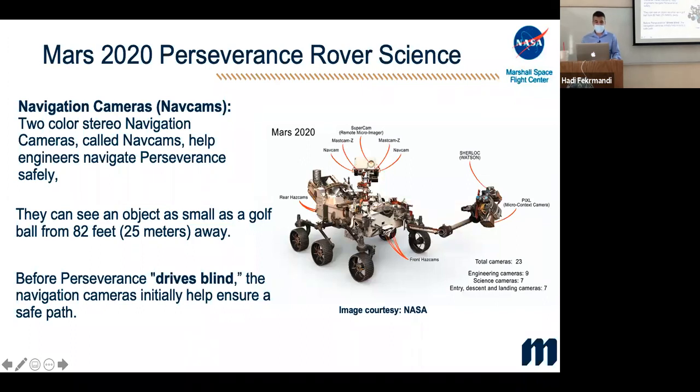calculations. But even that being said, between the two, it does dead reckoning. That's when it uses the odometry of motors to estimate where it is located. And there has been research at a couple of NASA centers that shows that this positioning of the rover, I mean, there's a slide that happens. If you follow the Curiosity, the wheels are almost ripped off because of the terrain, and those slips are happening, and it is very hard to have a localization of the robot.